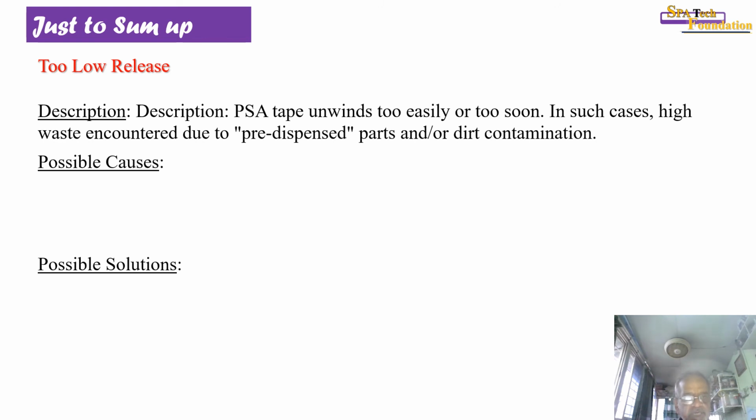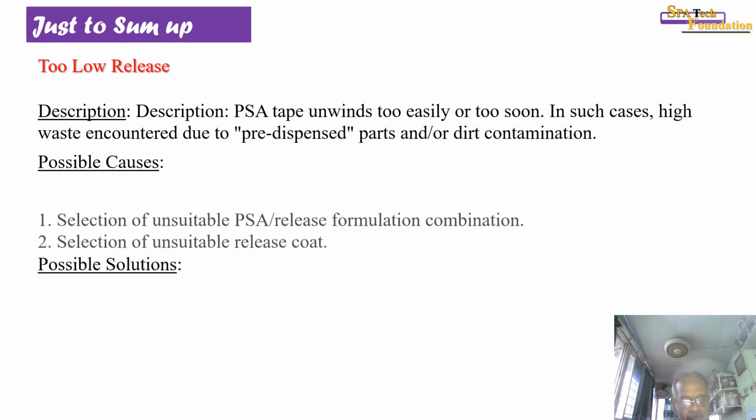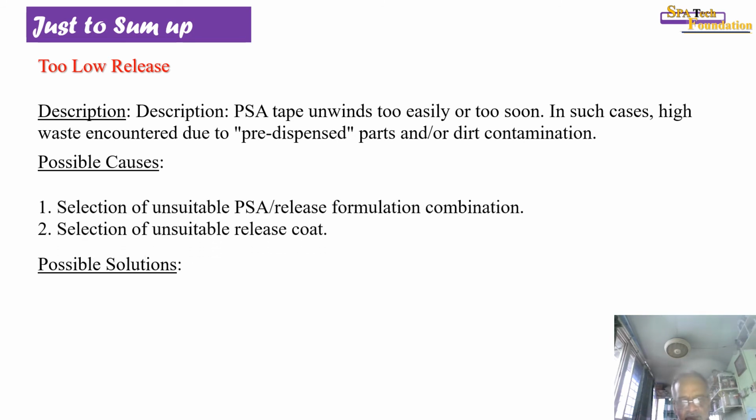Too low release. The PSA tape unwinds too easily or too soon. In such cases, high waste is incurred due to pre-dispensed part and/or dirt contamination. The possible causes: selection of unsuitable PSA, selection of unsuitable release coat, or too low adhesive coat weight.